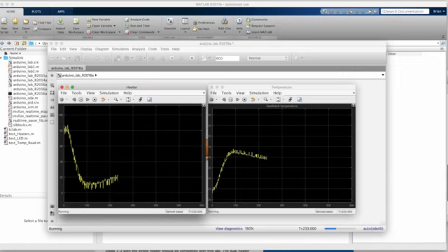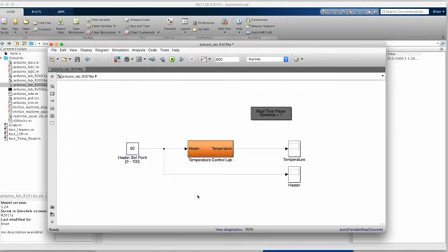When the temperature is steady at 40 degrees, we can see the heater set point is steady at around 17%. This means that the heat that is supplied at 17% is exactly the amount of heat that is lost to the surrounding environment. This is the portion that our heater makes up. So you might be tempted to just go back to our open loop system and set the heater to 17% and be done. However, this will only work if the environment stays the same.